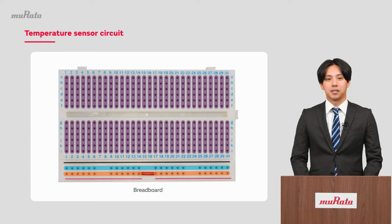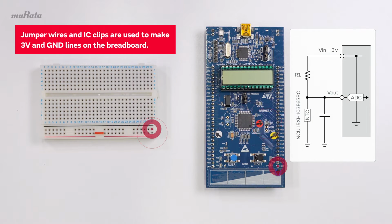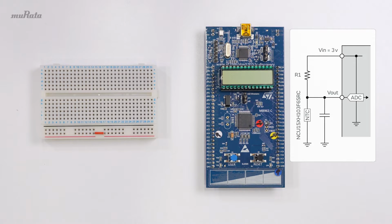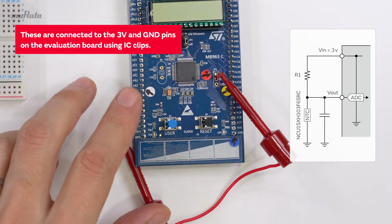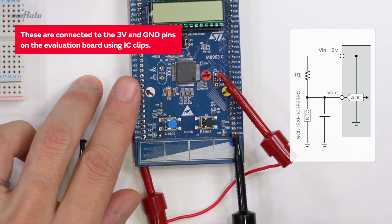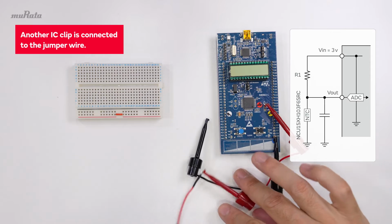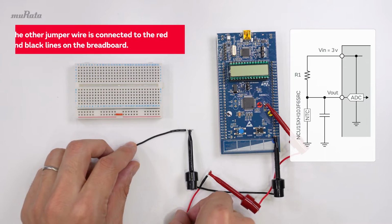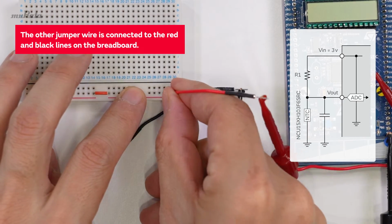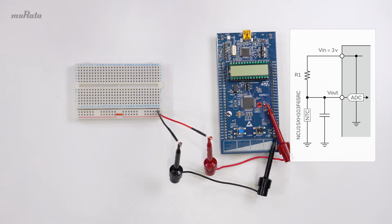Now let's create the circuit. First, we'll use jumper wires and IC clips to make 3V and GND lines on the breadboard. We'll use IC clips to connect to the 3V and GND pins on the evaluation board. We connect the other IC clips to the jumper wires. We connect the other ends of the jumper wires to the red and black lines on the breadboard. Here, we have created the 3V and GND lines on the breadboard.